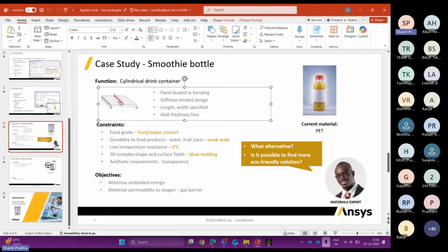So using the selector, material selection is like the first stage of your process. Before you start the design, you will have something like mass per unit stiffness. And if you change a material, you will get how much reduction in mass per unit stiffness. Maybe a 10% reduction or something, that you will get as an estimate. If you are okay with that estimate, use it. But in this presentation I did not include the design.